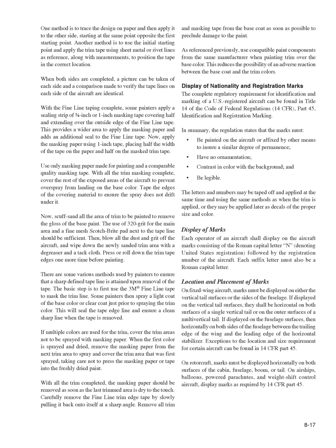The letters and numbers may be taped off and applied at the same time and using the same methods as when the trim is applied, or they may be applied later as decals of the proper size and color. Display of marks. Each operator of an aircraft shall display on the aircraft marks consisting of the Roman capital letter N, denoting United States registration, followed by the registration number of the aircraft. Each suffix letter must also be a Roman capital letter.